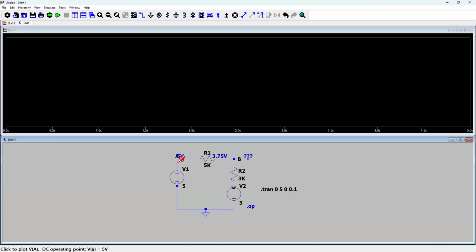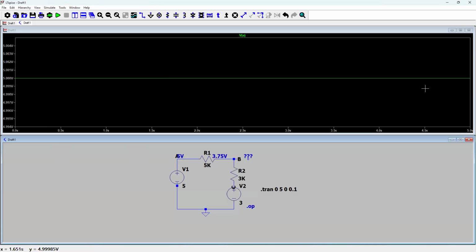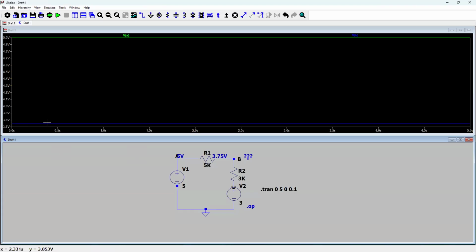I can put a capacitor and show you what I mean exactly. But for now, the good thing is, look, the cursor became like a probe. So once I click here, it is going to draw the voltage here. Once I go here, it is going to draw the voltage here as well. So this one is a voltage, this one is a voltage. The interesting thing is, once you come over the resistor, you can see the direction of the current assumed. Here they assume the direction is this way. You see what I'm saying?